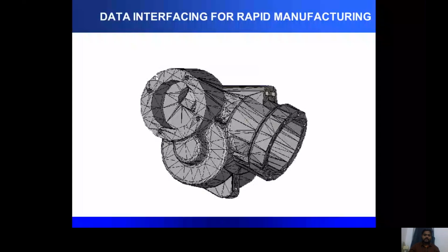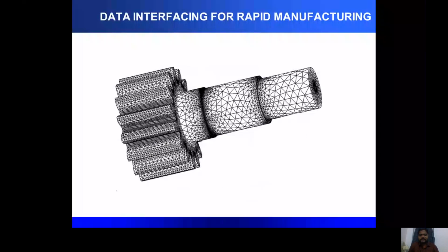This is another format. If you look into this file, you can also relate it with finite element analysis. In finite element analysis, we divide the CAD model into a finite number of elements. Right? The same procedure we are adopting for STL, but in FEA, while dividing a model, each element represents material properties as well as other properties required for finite element analysis.